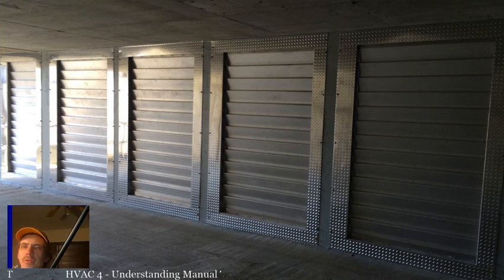Thermostats. There's certain thermostats you're not going to want to use with an infrared heater because it's not going to do a good job of sensing or of turning it on and off. And a typical room thermostat isn't going to be something you're going to want to use with an infrared heater, because the infrared heater heats surfaces, so it'll heat that room thermostat before the room gets heated. So read through your book on what thermostats tend to be better with infrared heaters.